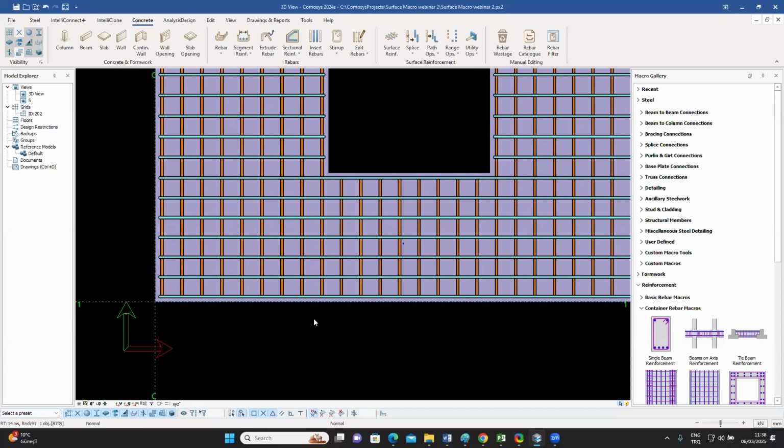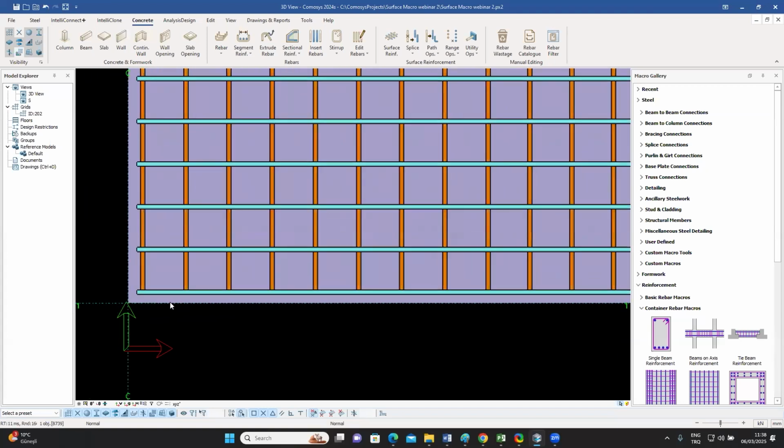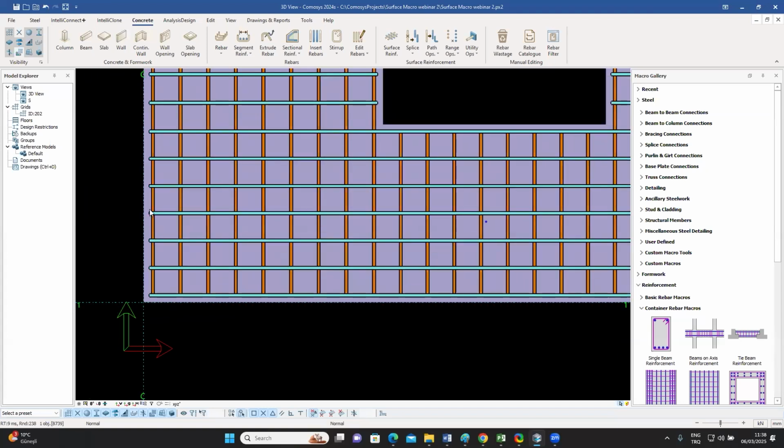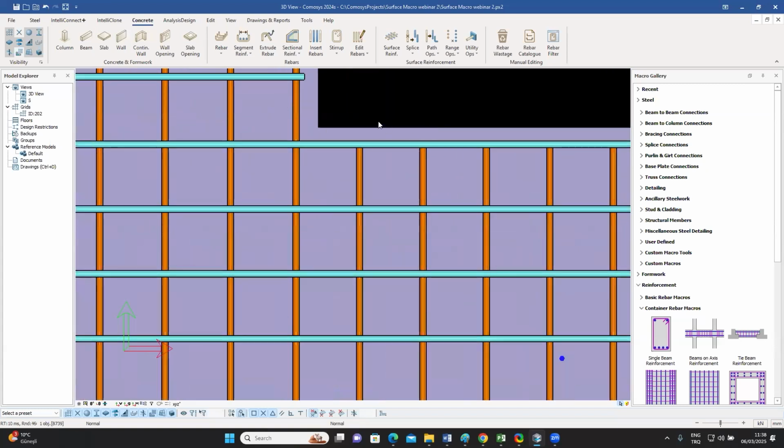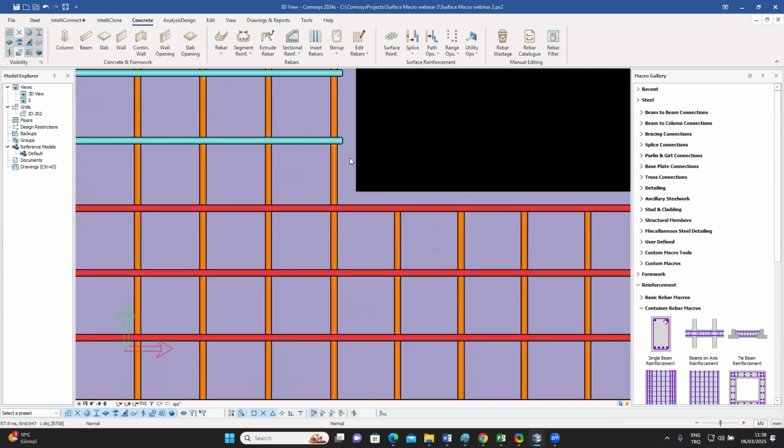Normally with many software programs, the program will start off with the correct clear cover at this point. But then whatever your spacing is, maybe you get over here, and with this hole you don't get a bar exactly at the clear cover point. So what they will do is you might have a bar over here, and the next bar will be over here somewhere.